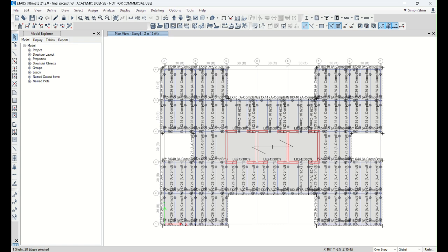Yeah, we do need some beams, but at this point we just focus on the composite framing beam. But I want you to be aware of it. Don't forget to mention it when you present this to someone. In a high-rise building, we understand that two egress stairs and elevators should be there, but we are focusing on the structural design, so you don't have to draw most openings. But at least acknowledge that this core is all concrete construction.